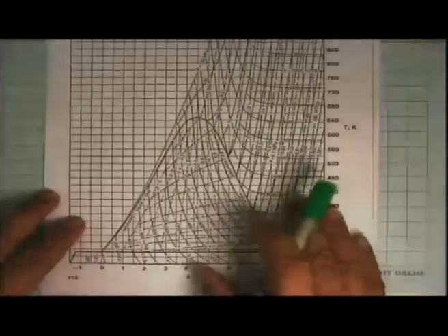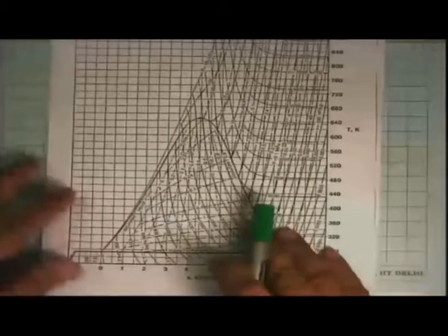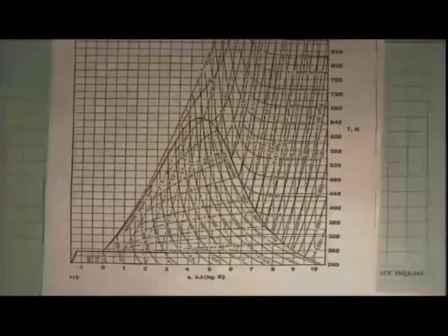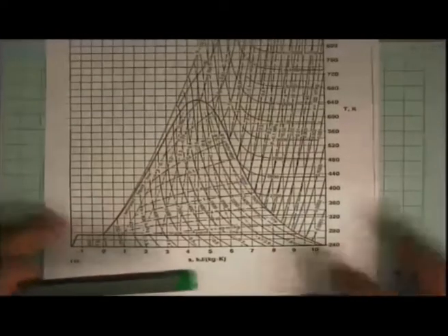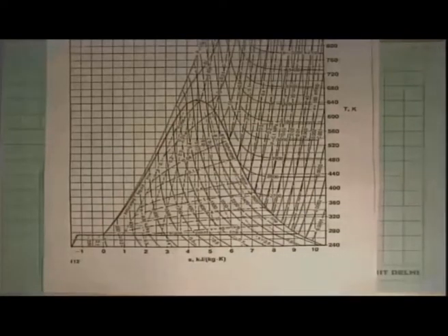Okay, so this is the thermodynamic properties of water. And again, now let's see what use I can put this to. And I pose a question that in a refrigerator we use 134A or R22, or in the olden days there was ammonia. Why can't I make a refrigeration cycle or an air conditioning system with water as the working substance? We have steam power cycles, all of them use water. Why not use the water in a refrigerator? And so let's begin to look at this. What will happen?